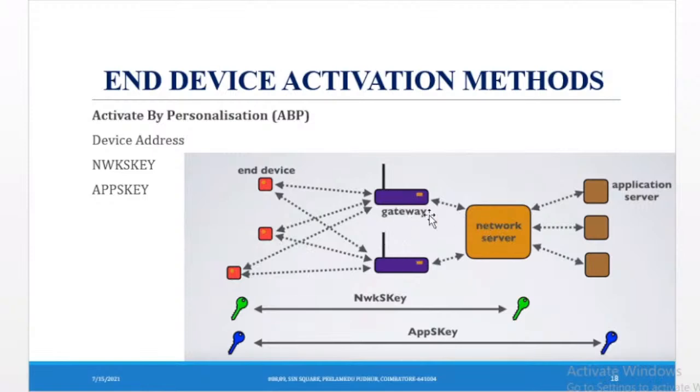What happened? The first data will be received from the number one gateway itself. The number two gateway is also sending the same data. So it will consider the first data and make the second data a duplicated data. So that is another main advantage of the network server. The first one is encryption and decryption, and the next one is data duplicacy avoidance.